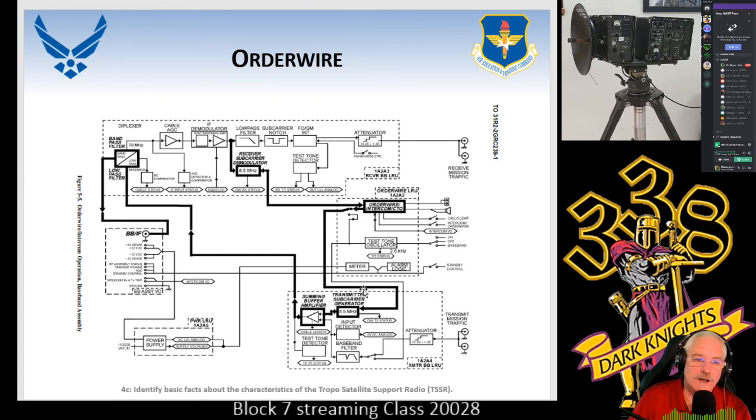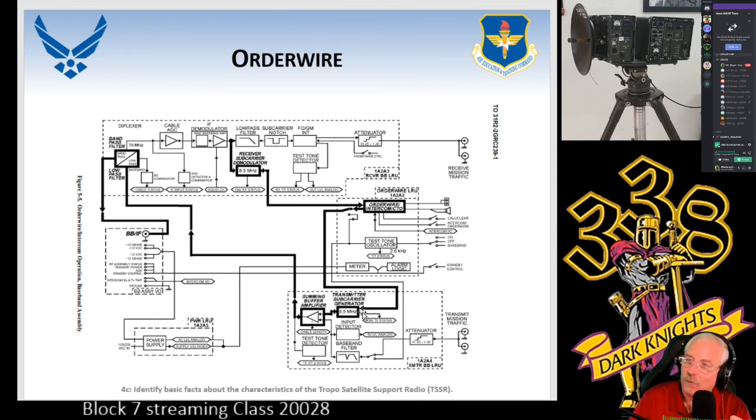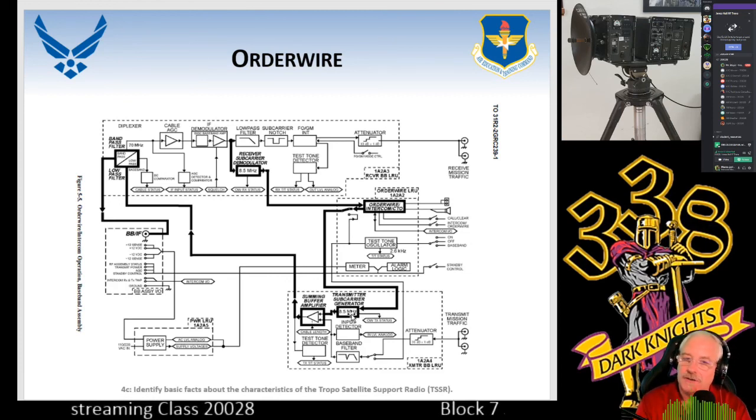With this transmitter subcarrier generator, you're taking your voice and, when you're transmitting, converting it into an FM signal at 8.5 megahertz. There's a discriminator in here, so you have modulation to FM.